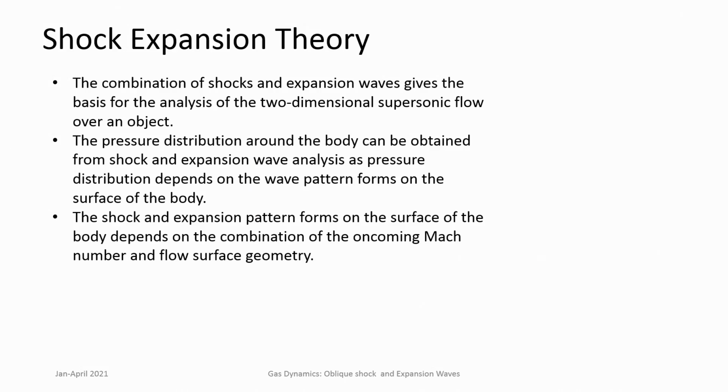So, this gives us a method to calculate the pressures that are going to be acting on the surfaces of bodies in supersonic flow, and from there, if you know the pressures, you can always calculate the forces, that is the lift and the pressure drag forces of bodies.